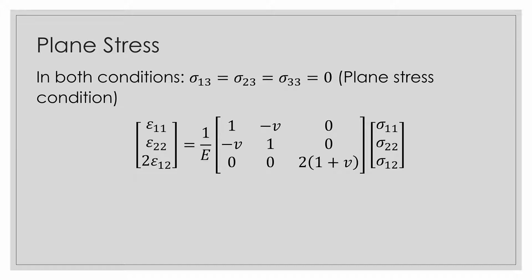Now, the one thing that we're going to have to keep in mind with this plane stress assumption is there actually is an epsilon 3,3. It's not going to be determined through the following relationship, but its own separate formula, where epsilon 3,3 is simply the negative Poisson's ratio divided by E multiplied by sigma 1,1 plus sigma 2,2. So again, V and E we already know, and by this stage we also know sigma 1,1 and sigma 2,2. So from the plane stress assumption, we can very simply solve for all of the strains, which is exactly what these questions will want.